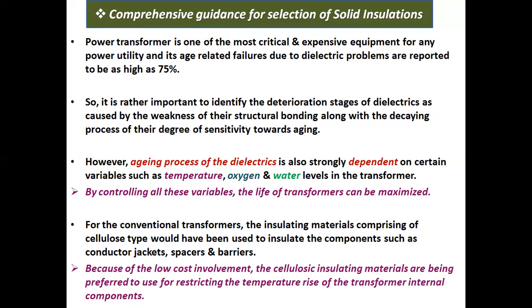However, aging process of the dielectrics is also strongly dependent on certain variables such as temperature, oxygen and water levels in the transformer. By controlling all these variables, the life of transformers can be maximized.